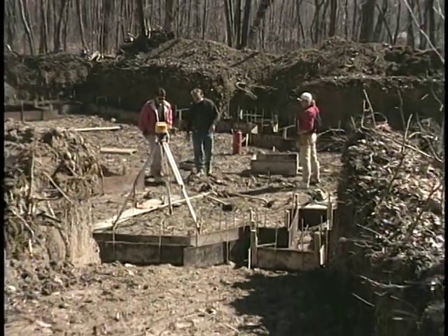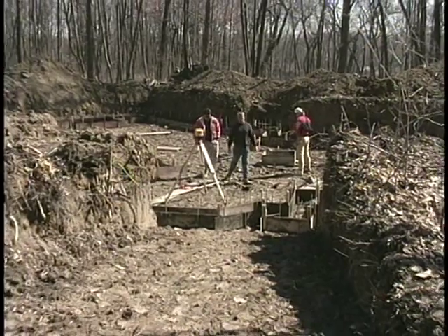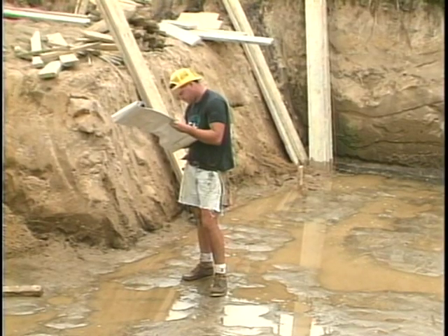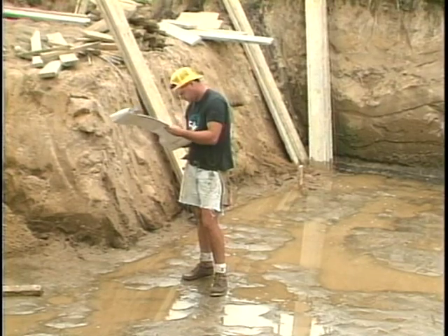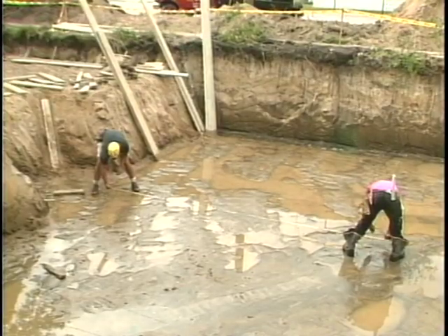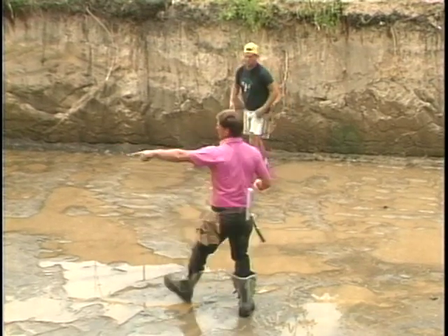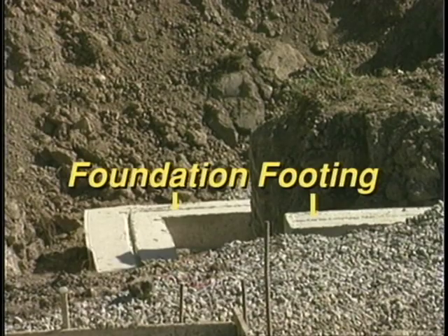After the excavation, you must lay out the foundation and build the forms for the foundation footings. If it has rained since foundation excavation, use an electric or engine-driven pump to draw water out of the excavation as needed. You can then lay out the forms for the foundation footing.